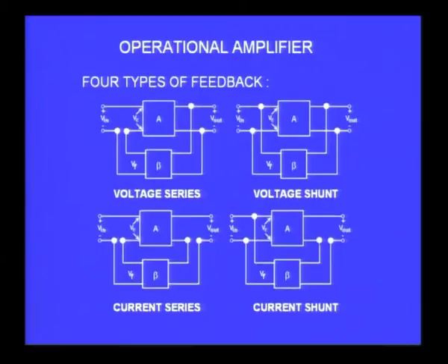Now in the present lecture we will move on to the next type of feedback circuit. You can see on the screen the 4 different types of feedback circuits again, shown for clarity. You might recall we did that in the last lecture also: voltage is sensed and given as voltage at the input, voltage sensed and given as current in the shunt form, current sensed in series at the output and given as voltage at the input, and current sensed and given as a shunt at the input.